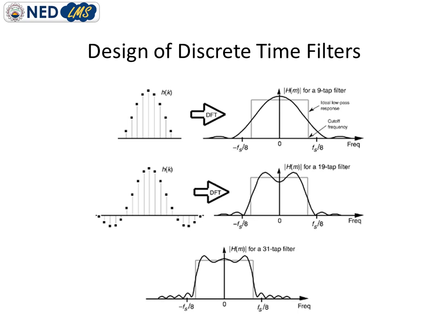But on the other hand, if we take back the DFT of this impulse response, to determine what this time domain representation is producing in the frequency domain, this response is basically plotting this solid line, which is not a very sharp low pass response. As you can see from the gray line here, this is the ideal response of a low pass filter.